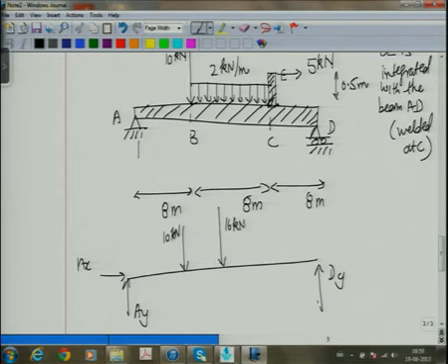And then, now, what do we do about this 5 kilonewtons? Now, we have to draw the free body diagram of the beam AD. So, we will write the equivalent of this 5 kilonewtons at point C. It will be a 5 kilonewton force and a moment which is equal to R cross F, so 0.5 into 5 kilonewtons acting in the clockwise direction.